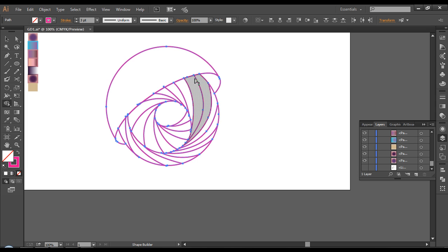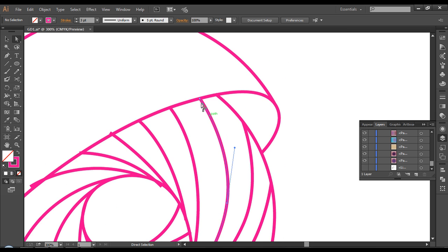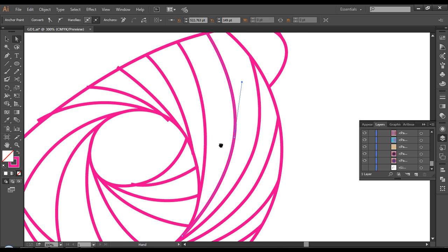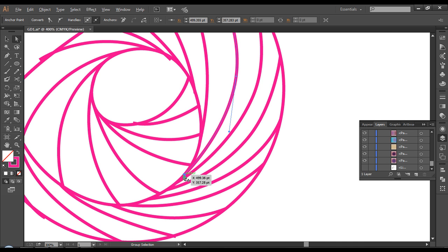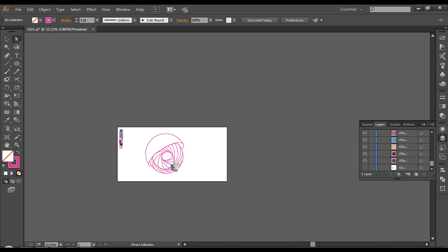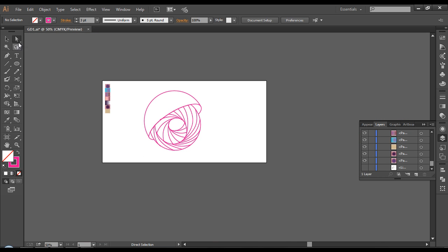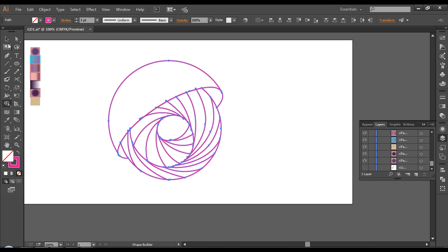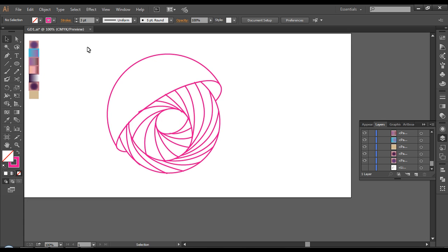Oh, here you can see some errors. If you don't do it properly, you'll see lots of this. So for this, we'll go in and make the adjustment. Just zoom in and let's select this and do the intersection here, and again selecting that, zoom in and do some adjustments here. If we check again and do the same, we'll get these separate pieces now. So here we have corrected that. If you find anything else like this, just go and correct it because it's important.